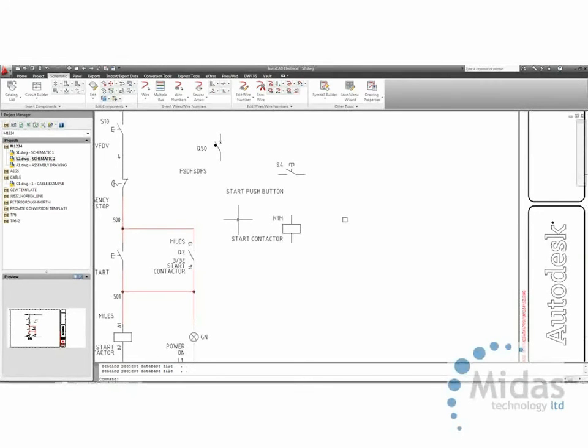We've also shown how we can create a panel layout from an estimate or just by placing parts down and then drawing our schematics afterwards. We're now going to show how you can manipulate the tags and any piece of information that you wish externally with AutoCAD Electrical and then import the revised data back in. Extremely useful for things like PLCs or where you're tallying up to the customer's existing tags, maybe in a P&ID circuit.